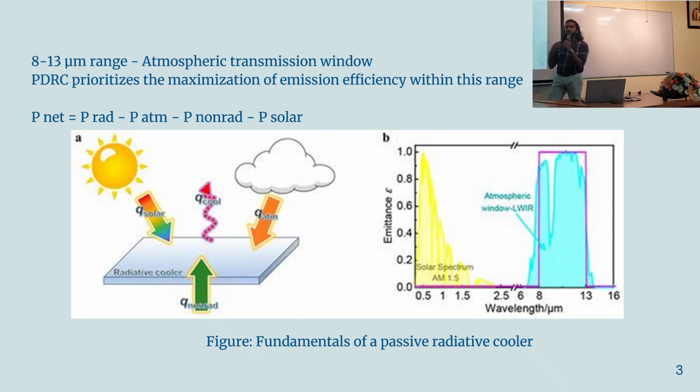So we would think now that we want to maximize emission, and to do that, we maximize the absorption. But if we maximize absorption, won't it get heated up by the sun? That is a valid question. But it won't happen here because the sun's radiation is outside of the radiation region that we optimize our material for. So it will not warm up due to solar radiation. It will take all the thermal energy of the material and emit it as radiation.